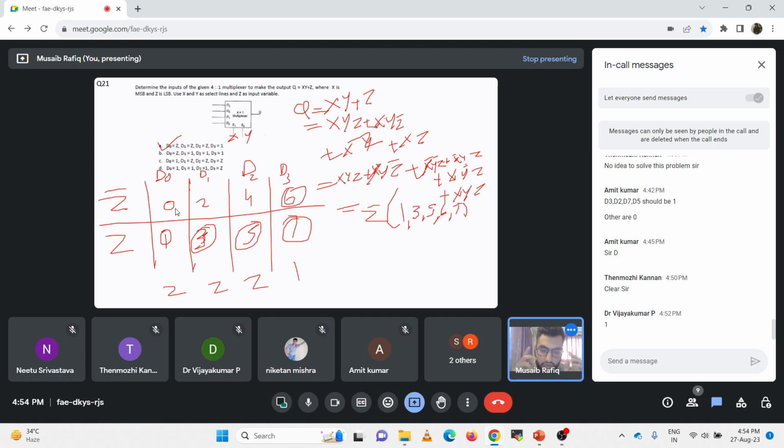So keep this in mind, because last year I was also a course TA for this course. We did examples like this, as you saw earlier, f of ABC, where A is your MSB and is connected to the input, and B and C are your select lines. But in one question, the LSB was connected to the input variable of the mux, and A and B, where A is the MSB, were connected to the select lines. So your implementation table differs from that case. So examine which is your MSB and where the select lines are connected. In the elaborative way, that time the question was given as a mux and you needed to find the output. Using the elaborative method, it takes 4 or 5 minutes, and you could have gotten the right answer even without any clue about the implementation. But the moment you want to construct using an implementation table, keep these things in mind.